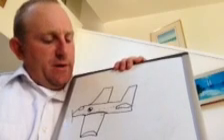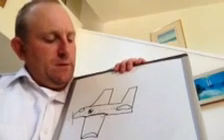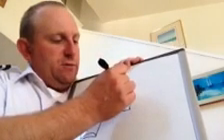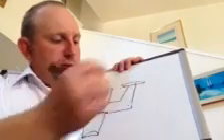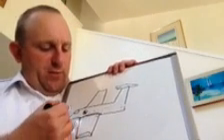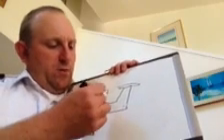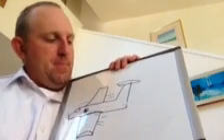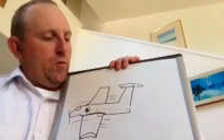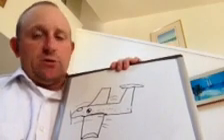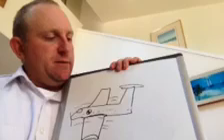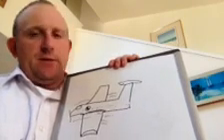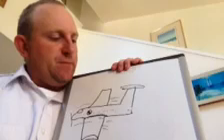Now, on the other hand, we have a T-tail, and a T-tail gets rid of the induced airflow from the propeller or any kind of jet wash that comes out. And what that does is it gives us a little more reliability in control as to what we can expect through a wide range of different airspeeds, because we don't have that induced airflow.